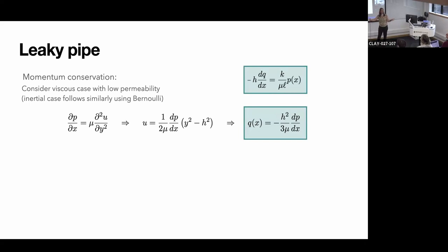I'm going to do the easiest one again, just to keep the algebra simple, but you can do whichever one you want. So this is laminar flow. For laminar flow, the shape of my velocity profile going down that pipe is parabolic. I'm now going to just depth average this to get a flux. So I'm going to integrate that, which gives me a Q, and that gives me my last equation. Okay, that was a crash course on fluid mechanics right there. And again, you can see how you could really put this on an exam.